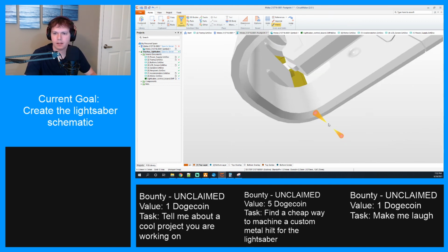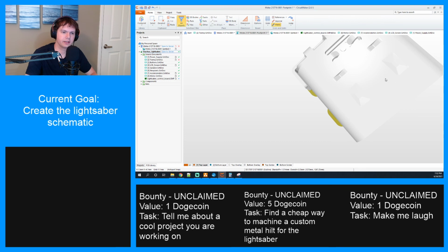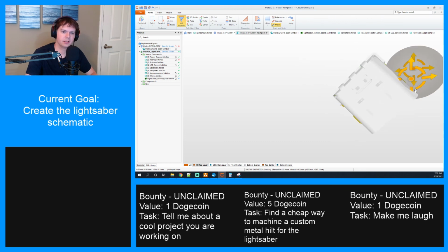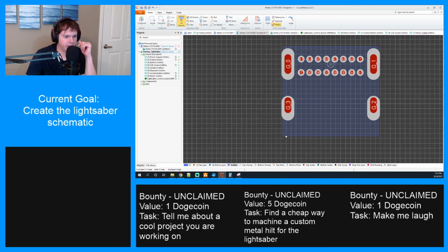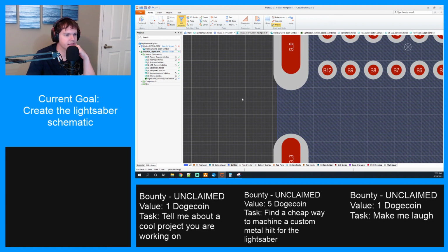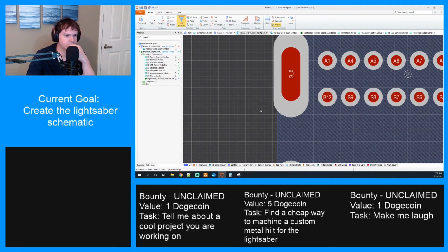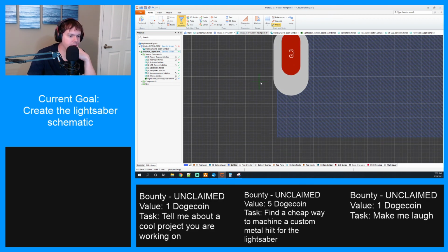All right, cool. So let me zoom out of this a little bit. Try and get this semi back to normal. Good enough. And then I'm going to draw a keep-out outline right along all the rest of this. Line. And I want this to be in the top overlay. I want a line.